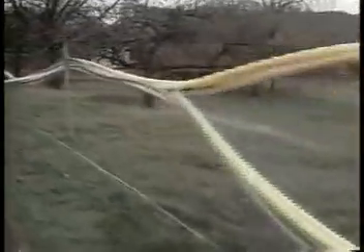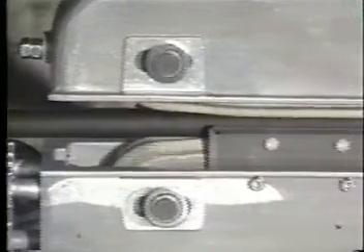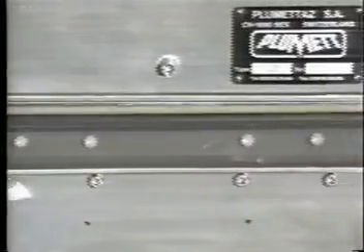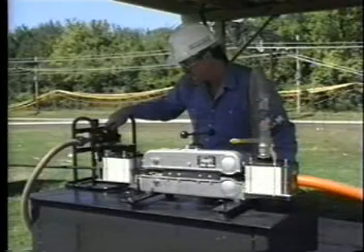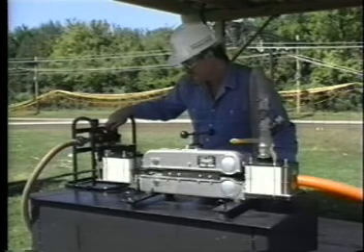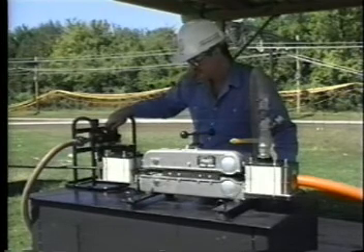This system is also independent of duct loops, curves, and undulations that would hamper conventional pulling. The hydraulic pusher is required to overcome the local resistance of the blowing head and its internal seals, and does not push the cable through the duct. It also acts as the controlling device for starting, stopping, and regulating cable speed.